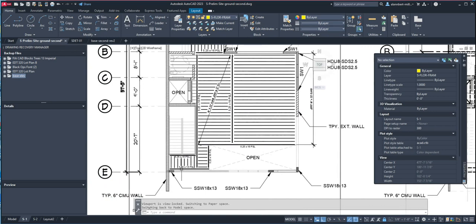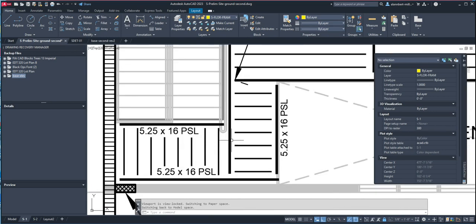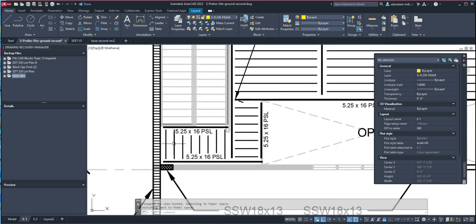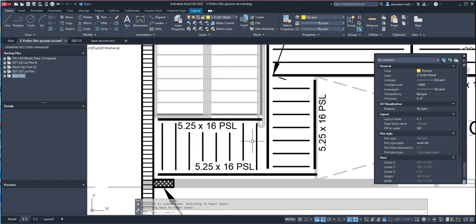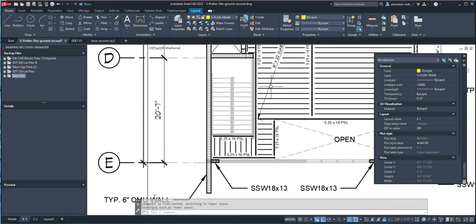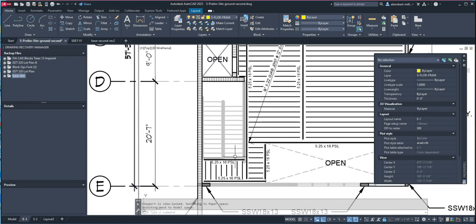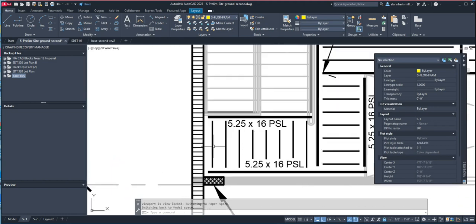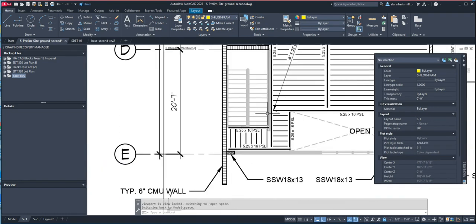And then if you look here, I changed the direction. And you can do that. Change the direction of the joist, because joists are supposed to span the shorter length, and this is shorter than this one, so I didn't span it this way. You change the direction because it's shorter, and you can also change the actual member. Okay, it's not going to be a 16 by 22 now.